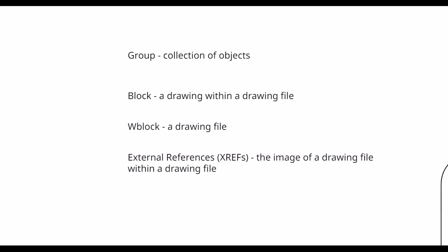Sometimes you have newborns and you just take photos of them every day, every week. So I think of an external reference as that image. And it will update whenever you open up the drawing file that it resides in. So if you just keep this concept in place, you'll be okay. And then I'll also point out that AutoCAD, when you highlight these external references and look at the properties, sees them as blocks. And it's fine, because it makes sense and you'll see.